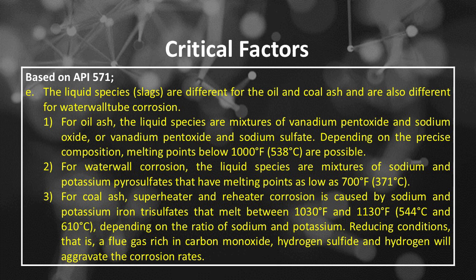Number 2: for water wall corrosion, the liquid species are mixtures of sodium and potassium pyrosulfates that have melting points as low as 700 degrees Fahrenheit or 371 degrees Celsius.